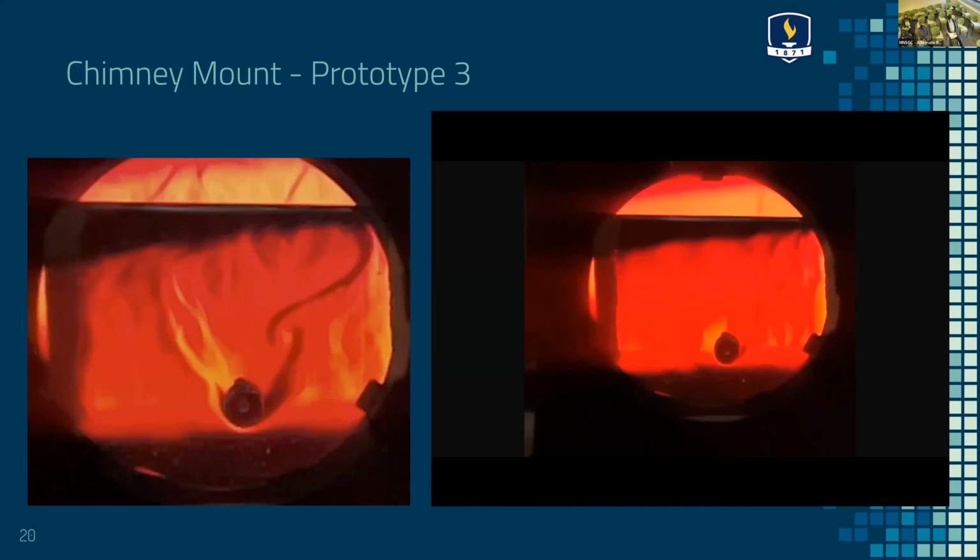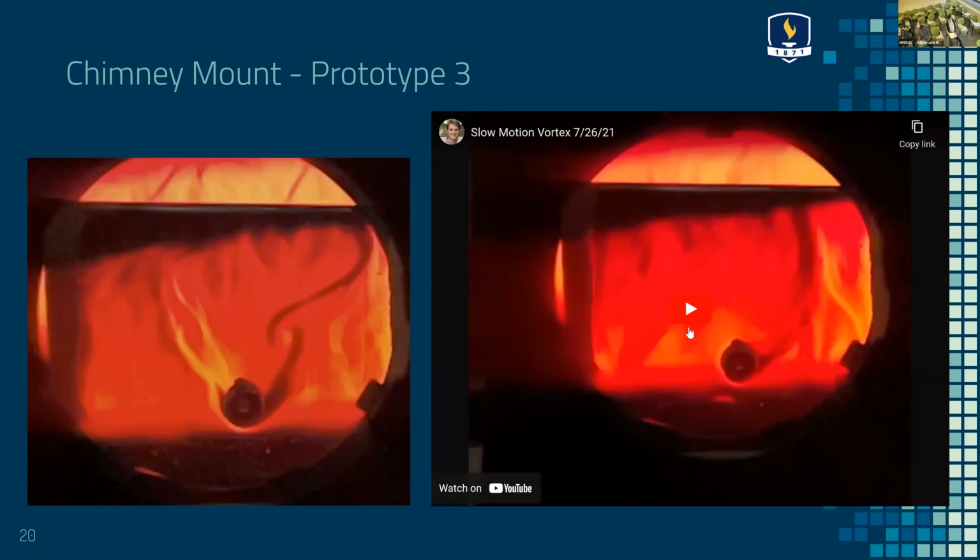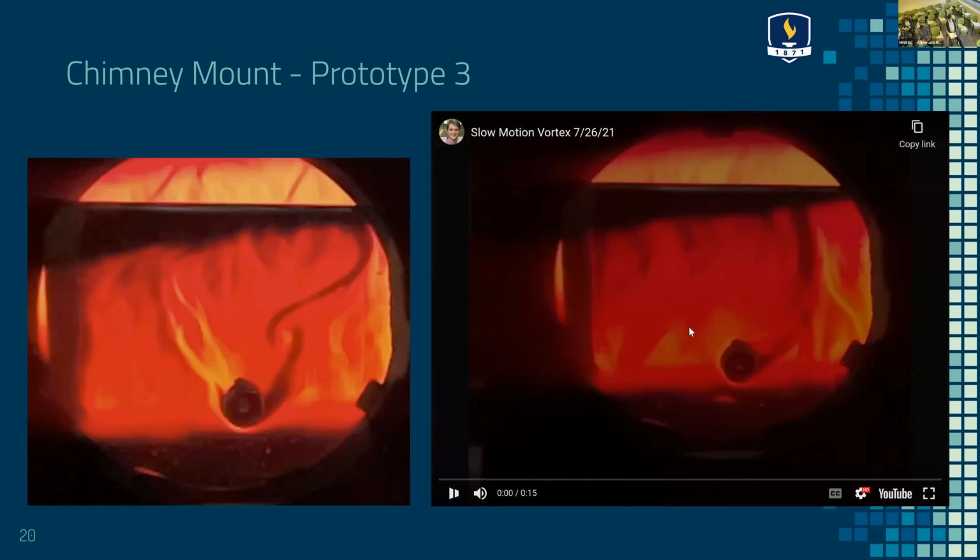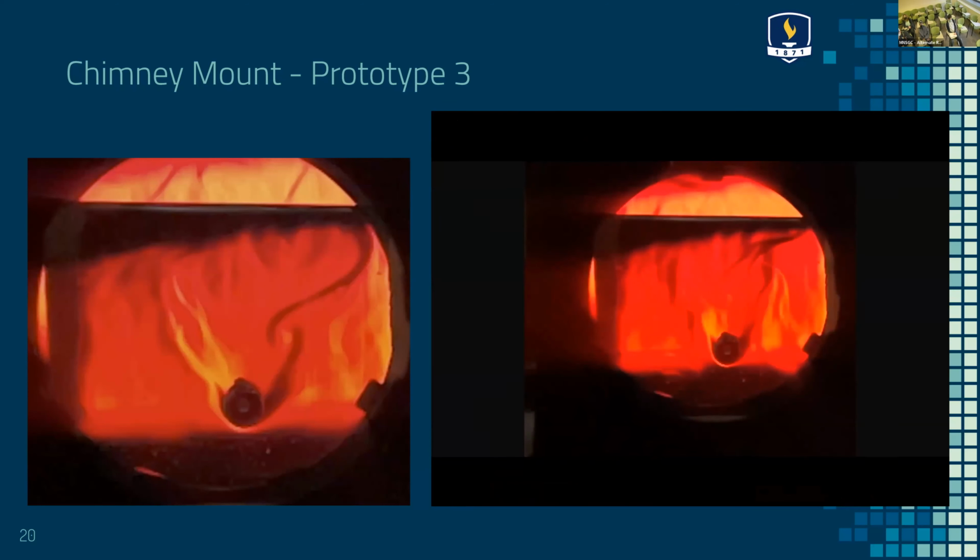By going in and tracing some of these little individual details and following that up with a scale on the side, we're able to work backwards, figure out a Strouhal number, and determine that we're actually starting to see some periodic motion within this system.